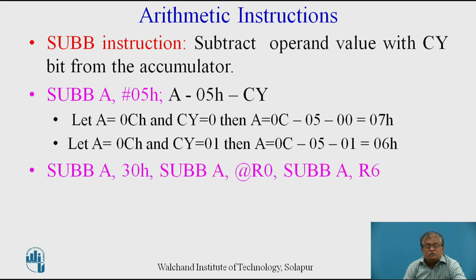It also supports various addressing modes. Direct addressing mode, that is SUBB A, 30H. The second example is for the indirect addressing mode, SUBB A, @R0. Then it also supports the register addressing mode.